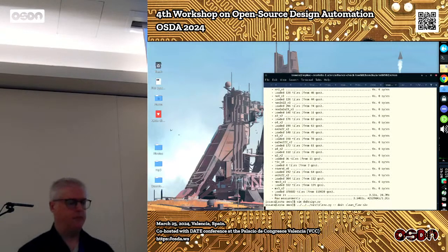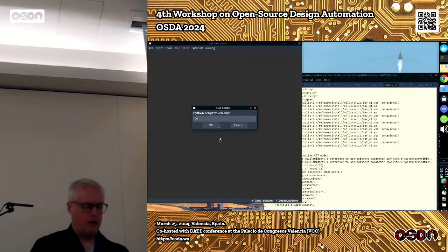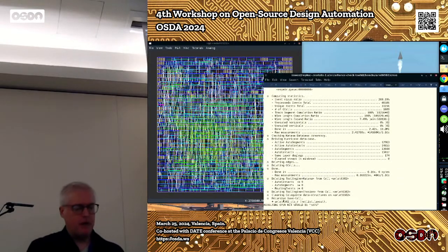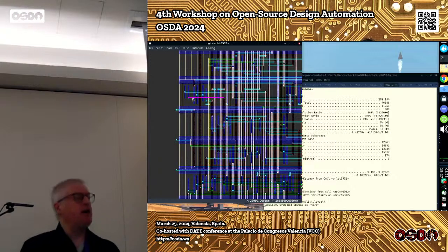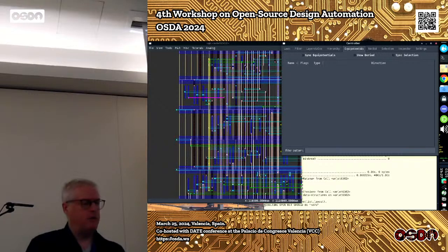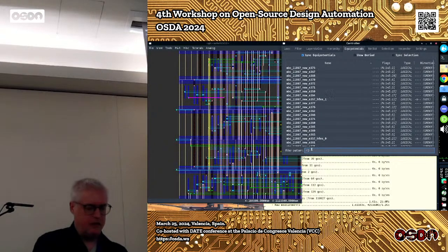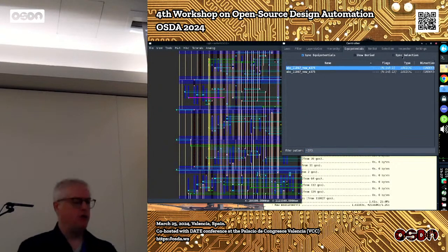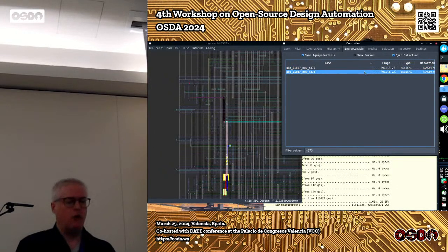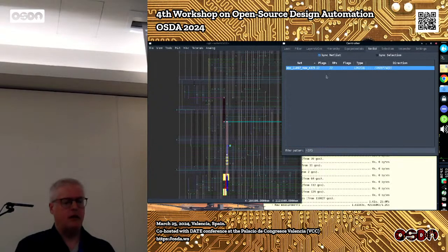Now I will break it. At the end of the routing, a violet line means that I did break something. So the database sees that we have unconnected things. I will perform the extraction again. You see two nets: one with the first part, with one only, and the second part with the rest of the net. And you can compare easily with the netlist here when you debug.